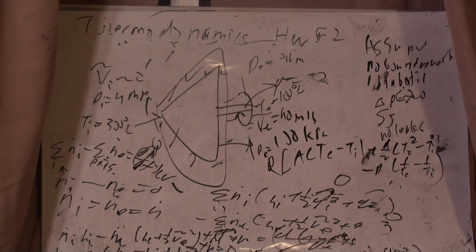So again, the molecular weight is about 29-ish, okay? And so I'm not going to have much of a velocity change. The energy change associated with the kinetic energy change is going to be negligible compared to what I have with respect to the enthalpy change.